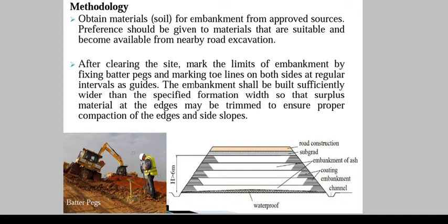After spreading the loose soil, it is compacted while maintaining the OMC. Sometimes you will observe the procured soil is wetter than required. The moisture content in the soil is more than it is required. At that time you need to spread it and allow it to dry. Wait for some time for the water to evaporate from the soil. Then you can check the moisture and compact it to the required density.